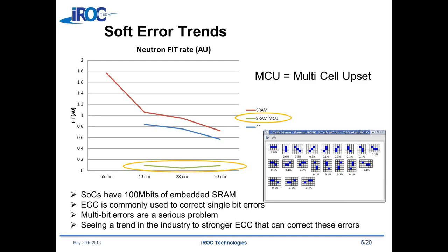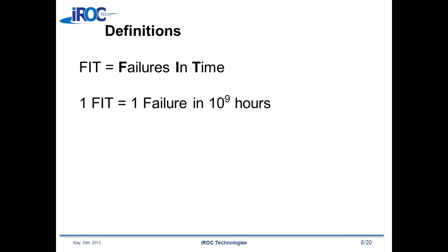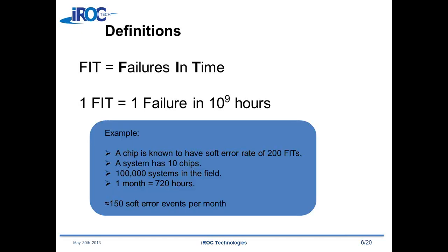You mentioned FIT rates a couple of times. Can you remind us what a FIT is? Sure. A FIT is a failure in time. So one FIT is one failure in about 10 to the 9 hours. Now, you might look at that and say, well, 10 to the 9 hours is a long time. My product lasts 10 to the 9 hours, I'm good. But I think you have to do the math and think about it.